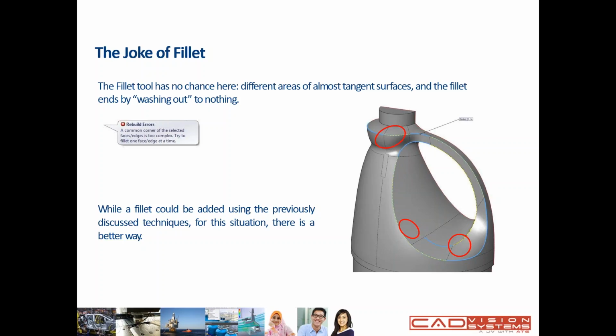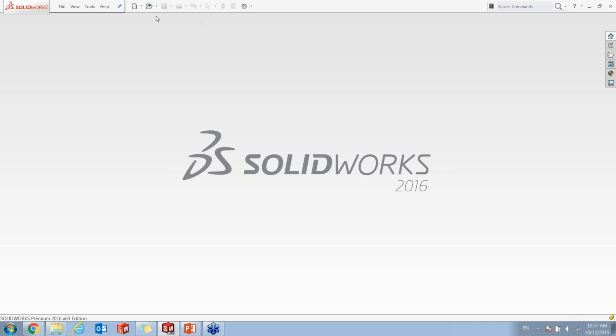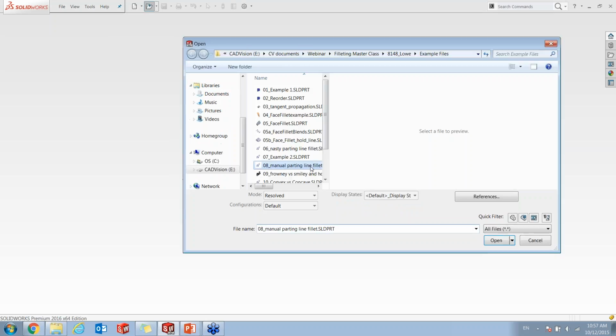It is like starting the fillet until the end, and then it becomes nothing. There is no face that can extend, no face that can end, no face that can change the geometry. So the only chance here we can create this sort of fillet is to generate a sweep surface and then make that fillet. Okay, let me show you in action how it's going to work.